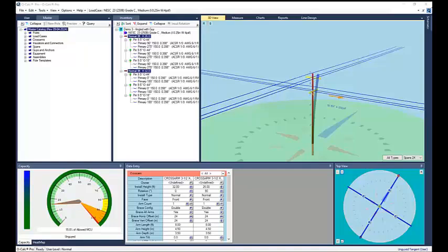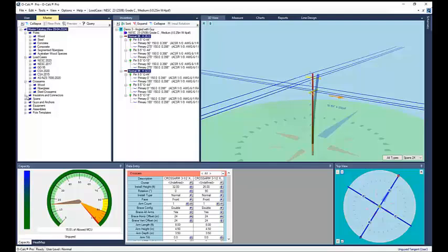When you log into O-Calc, you'll see on the left-hand side at this home screen a master catalog. Within the master catalog, you'll see subfolders. Within each of these subfolders, you'll be able to drag and drop equipment onto your structure that you'll see represented here in the 3D view and within the inventory. Within this catalog, you can build a pole beginning with any type of pole and then adding the regulations from the load cases folder. So what I'll do is demonstrate each of these.